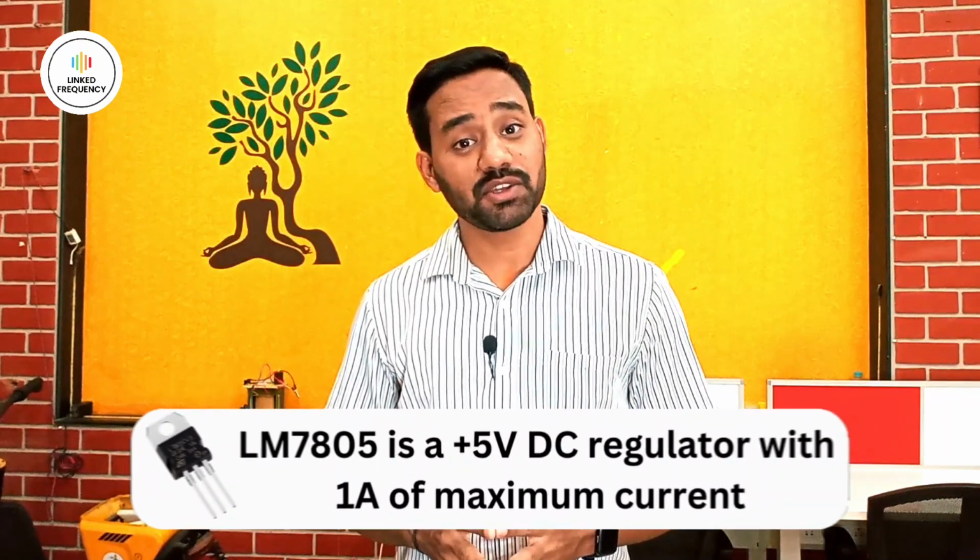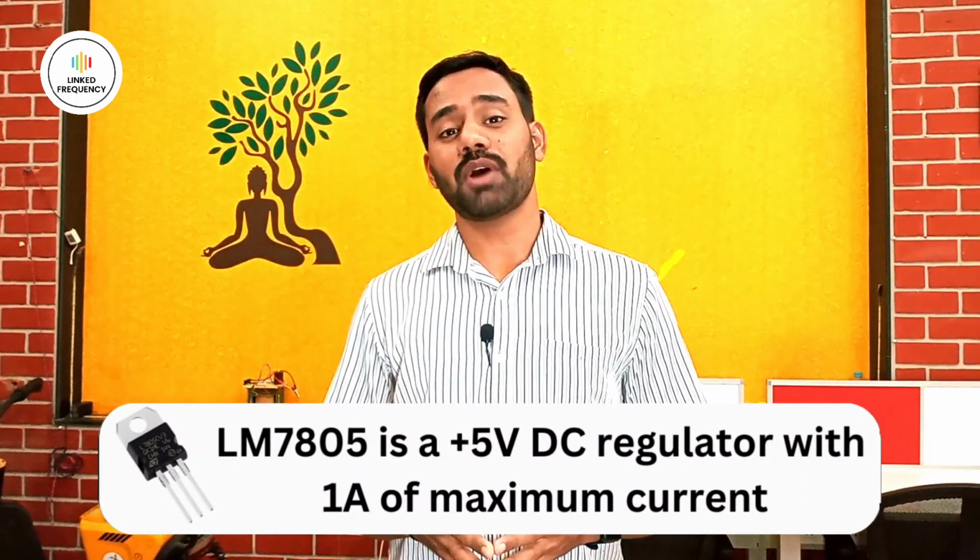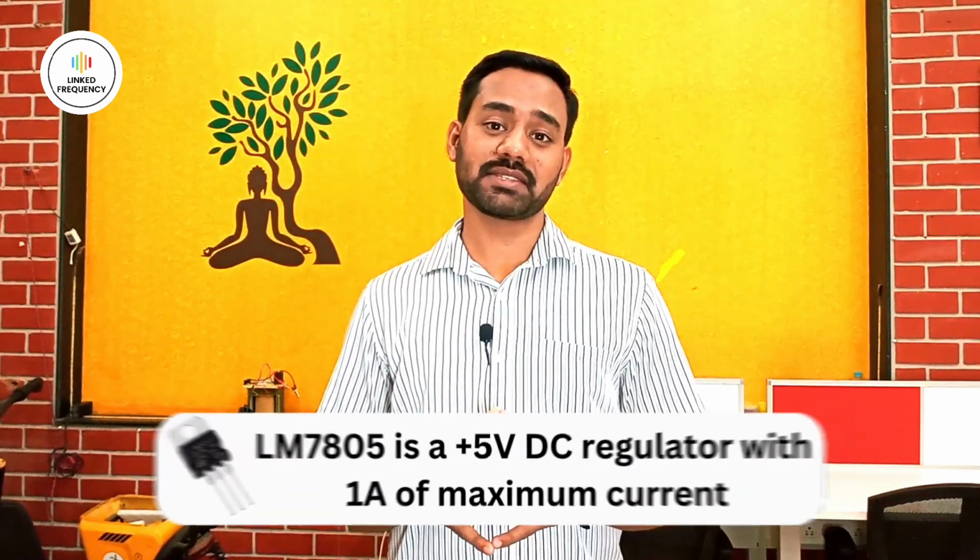In fact, you can even identify their thermal behavior or the quiescent current behavior and most of the vital information with respect to manufacturing of these regulators and requirements of using these regulators in your circuit. Here are the few points which I collected for the 7805 regulator from the data sheet for your understanding. First one is 7805 is the positive 5 volt regulator with a maximum of 1 ampere of current carrying capacity.